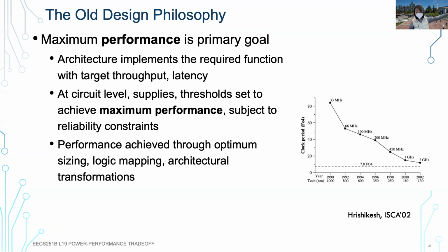If you look at before 2000 here, it's crazy. Just think about the clock delay. We're talking about roughly 7 or 8 FO4 delays. That's crazy, right? If you think about flip-flops, that's already 2 or 3 there. There's not a lot of computation. It's a very deep pipeline with not a lot of computation going on. That's where we were going when we projected to reach roughly 2 gigahertz. We're talking about just a couple of gates per stage to get very high frequency.